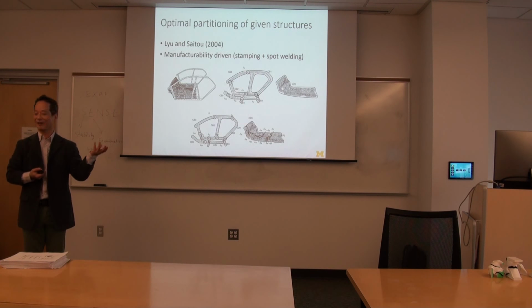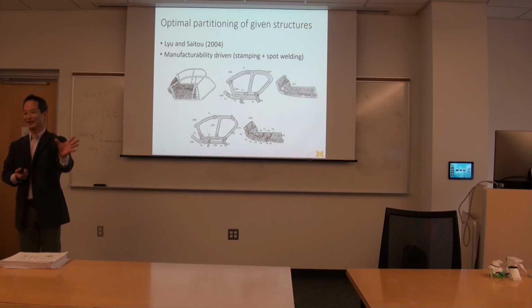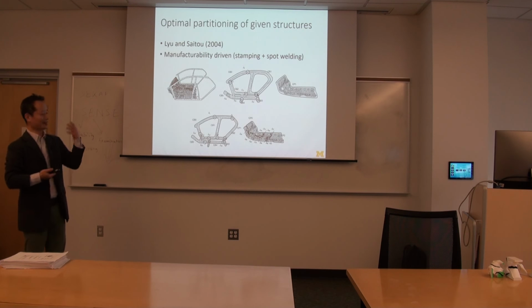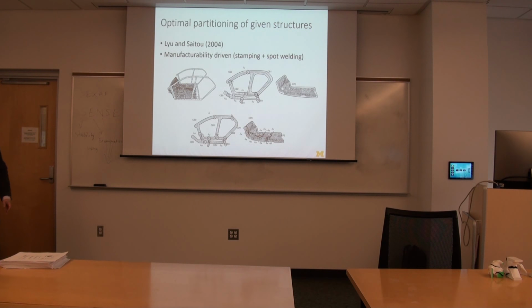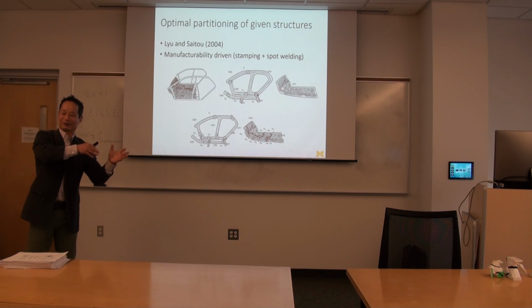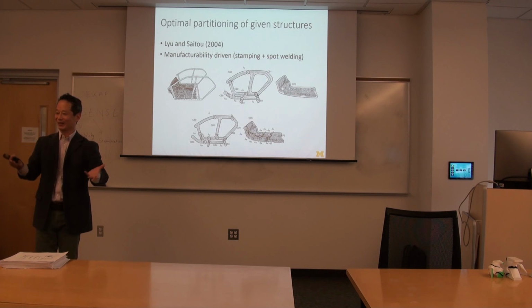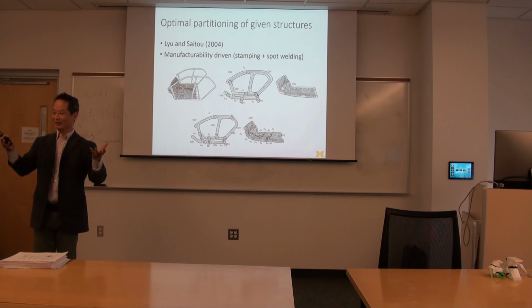It's a fixed geometry FE model of a one piece, say mid area of the body, and I just did the decomposition. Partition is the only thing we did. Again, applying this stamping and spot welding as a driver for partition. Of course, while you're doing it, you have to look out for the original specification of the product, which the